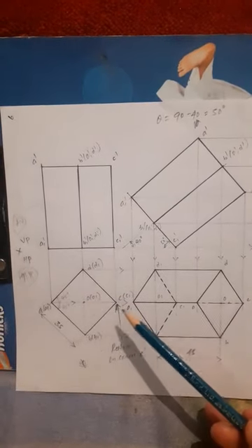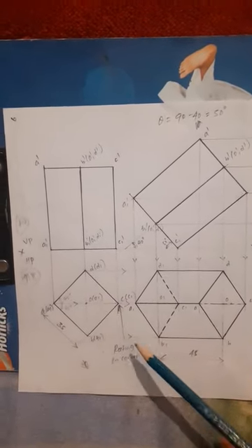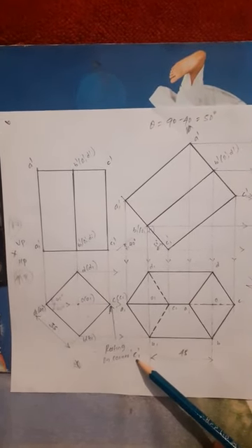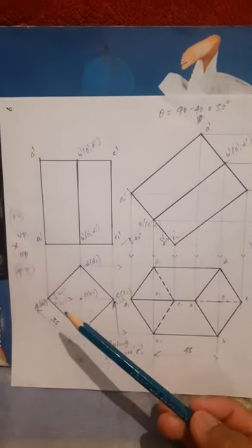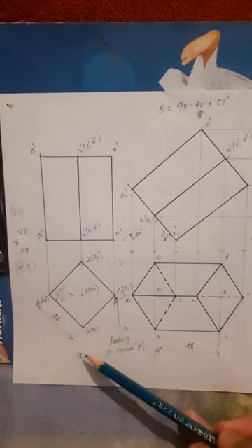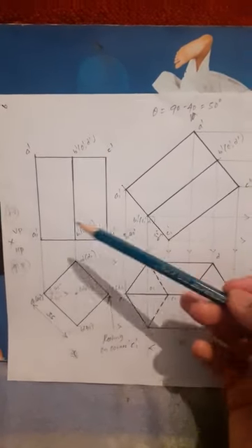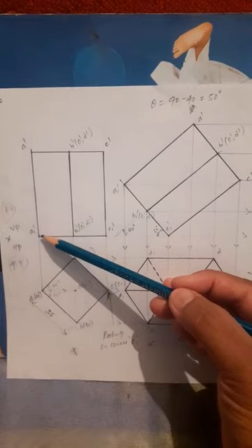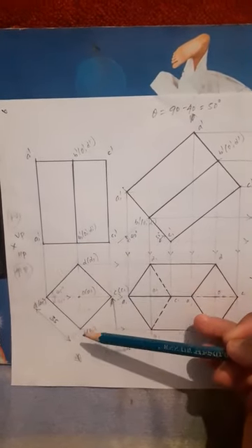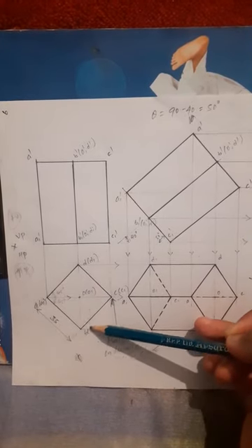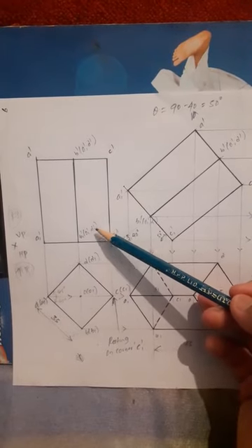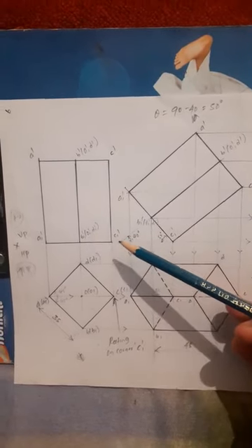Resting on HP means you draw on the horizontal plane, and resting on corner C1, this base corner C1, right? Then this is the first position, top view. Then view from here, this is the observer. When viewed from here, project all the corners vertically upward. For the base, A1 dash and B1 dash, B1 is near to the observer, visible. D1 is far away from the observer, invisible. There's D1 dash and O1 dash, that's why I kept them in brackets.